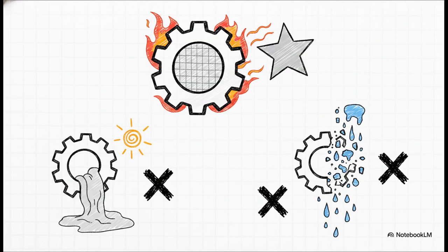Here is exactly how you nail the answer. Nylon 6,6 is absolutely the optimal choice. To get full marks, you need the right keywords. Explain that its high crystallinity creates tightly packed chains with strong intermolecular forces. That's what gives it the thermal stability to survive intense engine heat. And make sure to point out why the others fail. PLA would just melt and degrade at those temperatures, and ABS lacks the chemical resistance needed to withstand harsh engine fuels and oils.